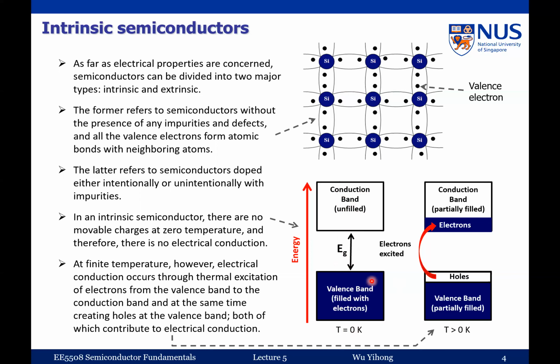So the valence band is completely filled up, so you don't have any empty states in the valence band. Therefore, when you apply an electric field, which is a driving force for any charged particle, electrons in the valence band are unable to move. For electrons to move, you must have vacancies, so that the neighboring electrons can move into the vacancy, which creates another vacancy for another electron to fill. By doing so, the electrons will start to flow. But when the band gap is finite and it's at zero temperature, this is not possible.